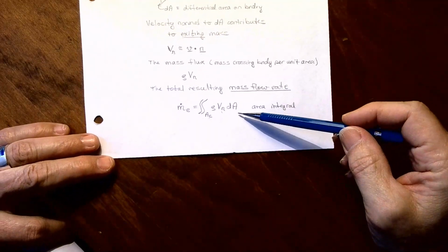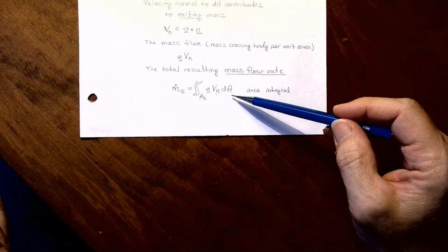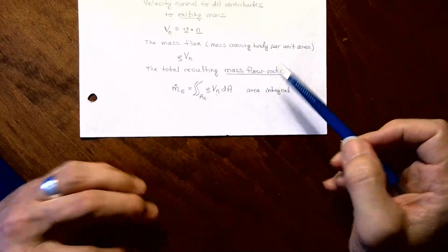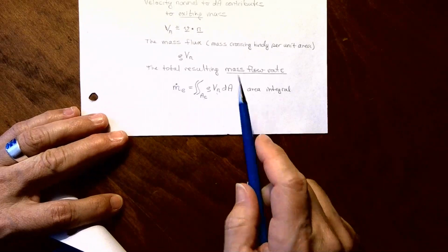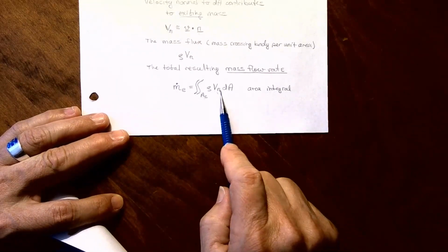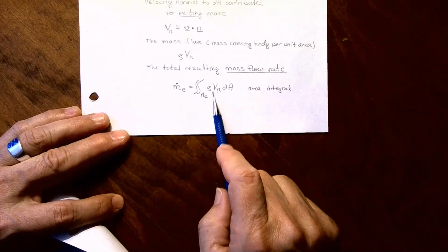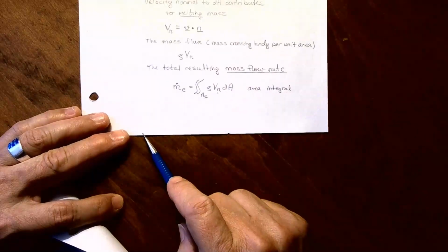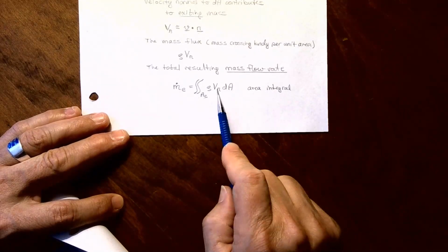Okay, so this is a general expression which is probably going to be the beginning point for students in a fluid mechanics course. In this course, as an intro thermodynamics course, we are always going to simplify our situation, and only consider velocities that are constant and densities that are constant over the cross-sectional area at a single port anyway. So these are going to be constants and come out front. And then if I integrate dA, you simply are left with the exit area. So we'll end up with rho times V times area.